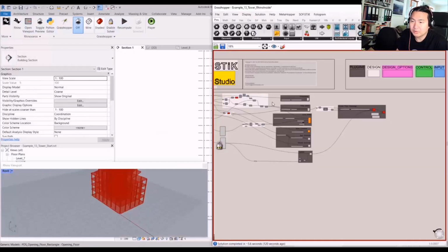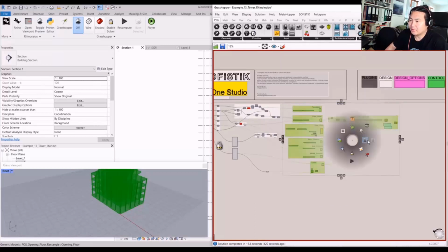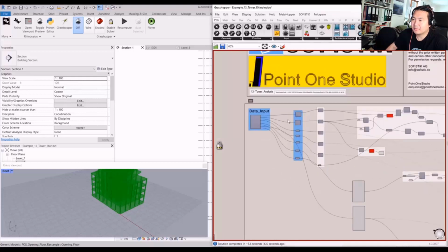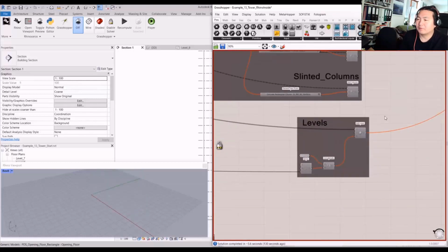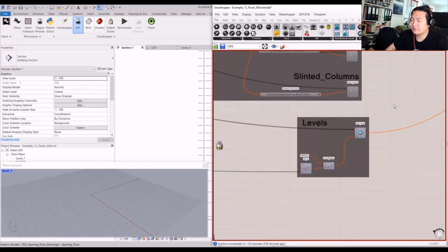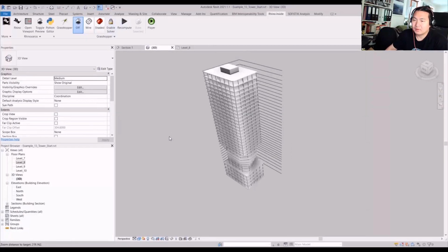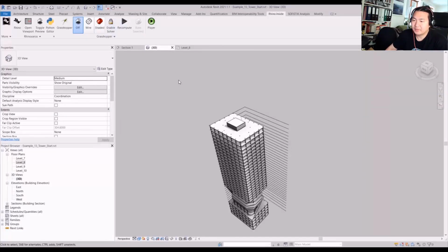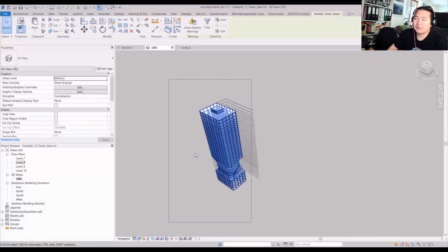I'm going to open Grasshopper again and disable the whole Rhino Inside component, because it takes some time when I change the design script, and I don't want to wait for all the updates on small changes. So just turn it off, and let's select all the elements except the levels, because I'm not going to regenerate the levels, but all the elements.